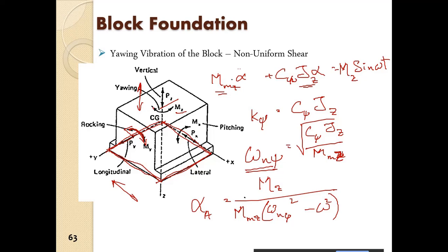We cannot consider this moment because it is out of this plane, so we will only consider whatever is within one plane. At any xy plane, whatever the forces are, we will consider at one plane, to simplify the calculation. We are not going to do a three-dimensional calculation. We are going to consider whatever forces and moments there are in one plane of action.